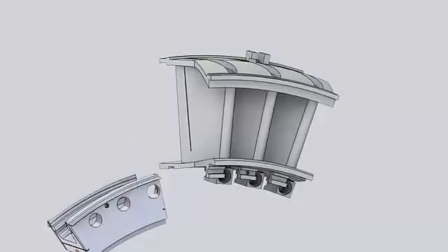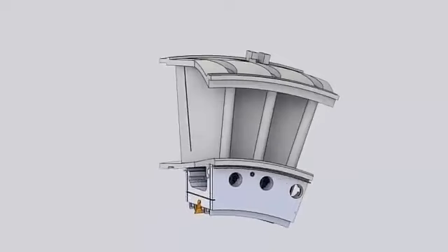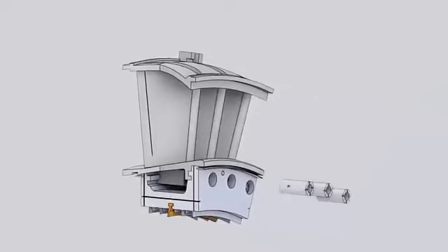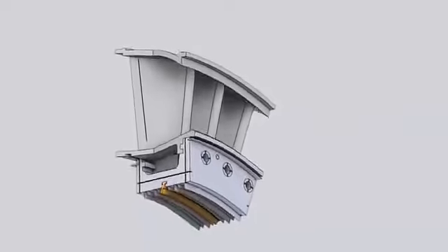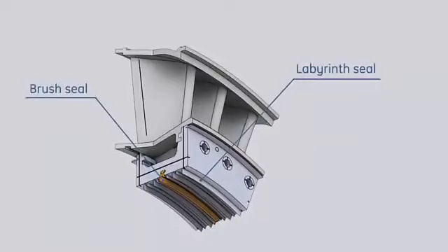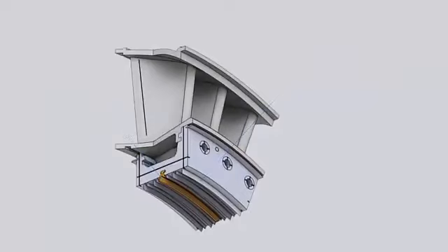Annular curved segments are attached to the inner sidewall of the nozzle. These segments are called the diaphragms. Each diaphragm is secured to the nozzle by a pin. These diaphragm segments prevent hot gases leakage past the inner sidewall of the nozzle and the rotor. A high-low labyrinth seal is machined on the diaphragm inside diameter. These seals mate with opposite sealing lands on the turbine rotor spacer.